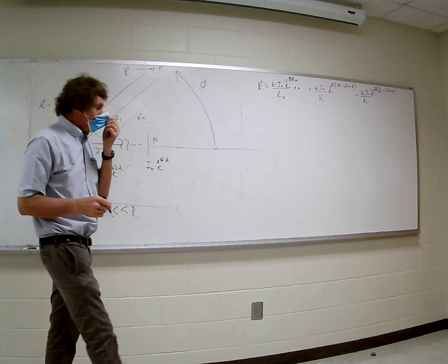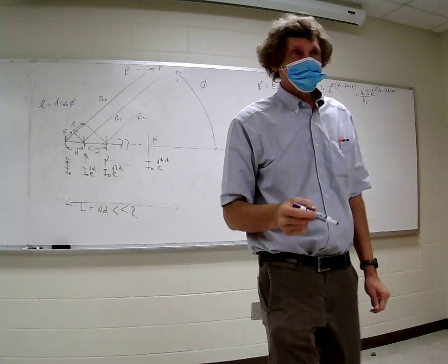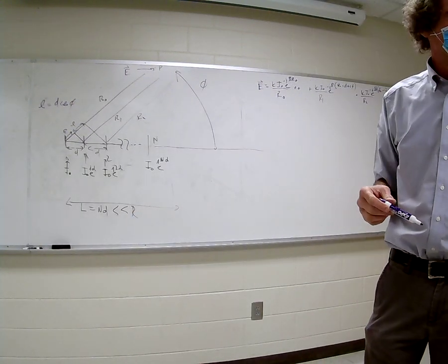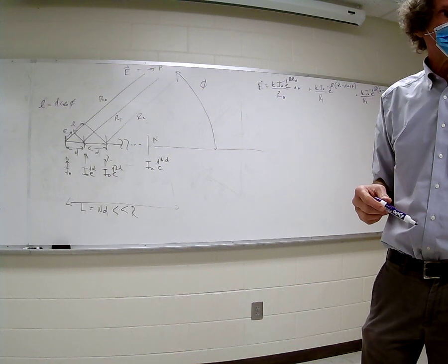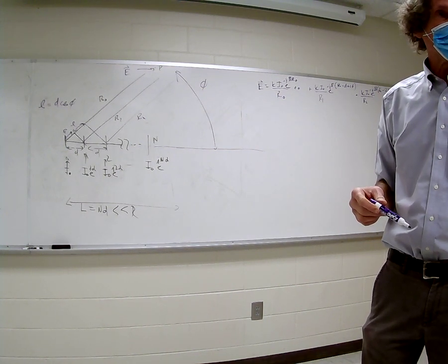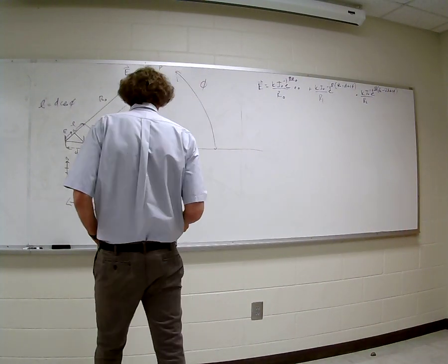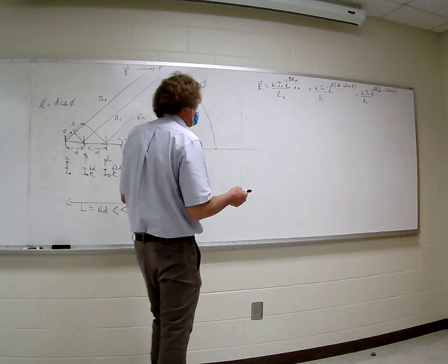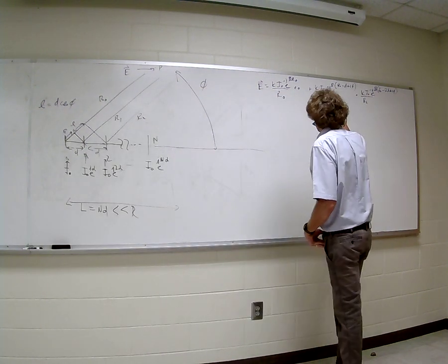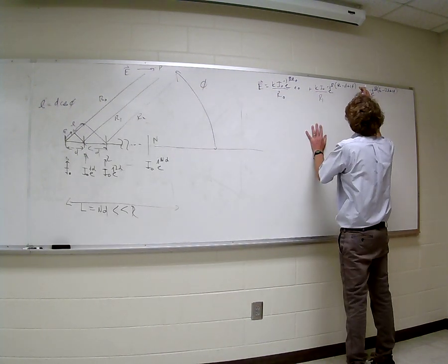All right. Now, something I forgot. Did anybody catch me with what I forgot to put in there? Look at the currents that I put down. What's the one thing I added to all the currents? Phase angle, right? Alpha. So what I actually have to do here is include that phase angle.